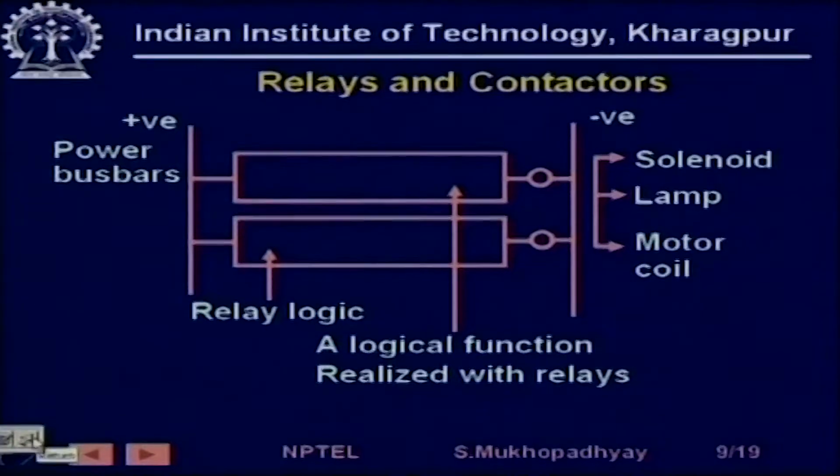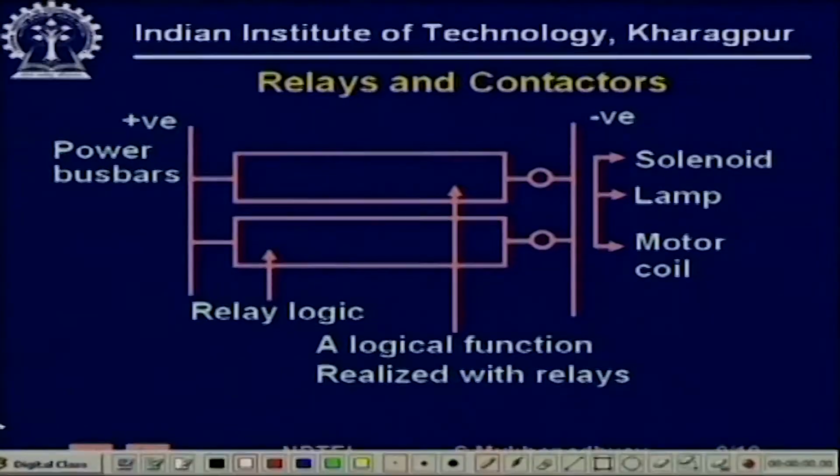So, we move on and we look at the predecessor of a PLC. Before PLCs were invented or made out of microprocessors, such sequence control problems used to be typically tackled using control panels, which typically employed things like relays, contactors, various kinds of switches, lamps, various kinds of electromechanical timers and such things. So, they were actually physical devices which were hardwired.